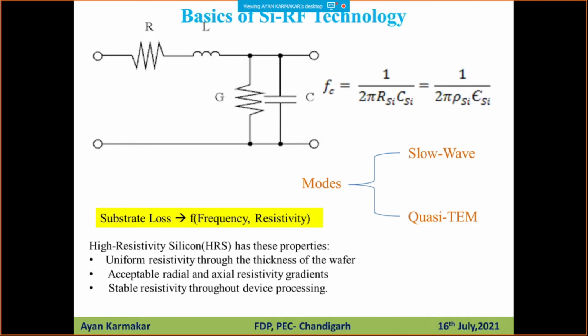This comes from the very basic things of transmission line theory. If you know the basics of the transmission line, you can model that substrate for RF or microwave uses. We know there are basically three kinds of losses whenever we talk about RF or microwave. One is conductor loss, another is substrate or dielectric loss, and finally radiation loss. If we are not talking about any antenna kind of circuitry, then you have to tackle this radiation loss somewhere else. Conductor loss is obvious for both low and high frequency, the I squared R loss.